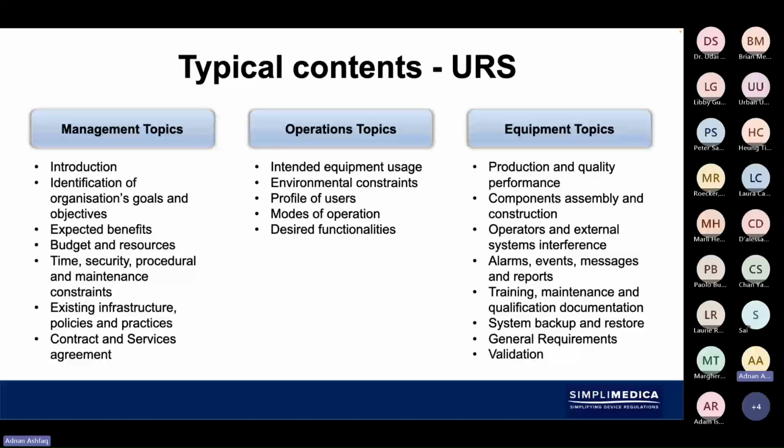And I have to say that user requirement specification on a whole is very often overlooked, because the number of projects that I get involved in where equipment needs to be validated has no history of any user requirement specification that you're trying to then match up a qualification exercise that needs to be executed. Typically, you would be looking at the user requirements, especially for something like a performance qualification. When we get to PQ, we'll be looking at some of the things that you need to consider, which would have been usually identified in the user requirement specification had it been done properly.